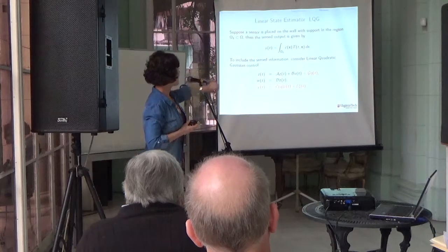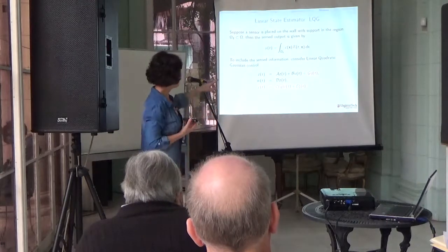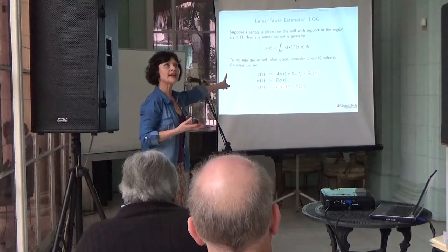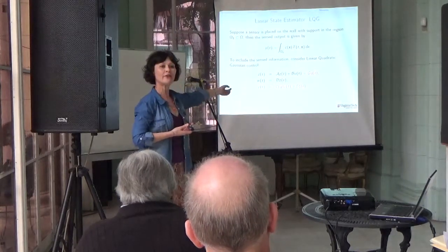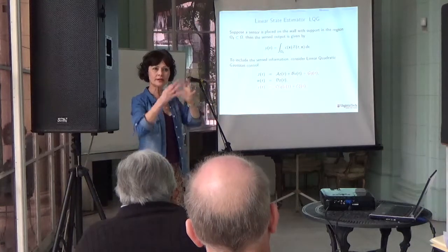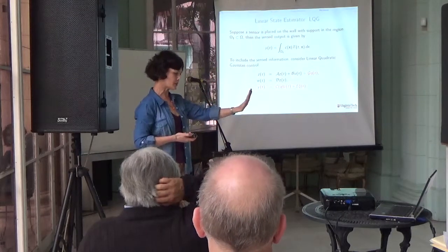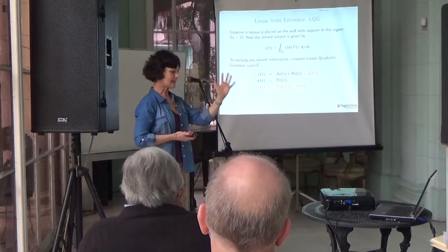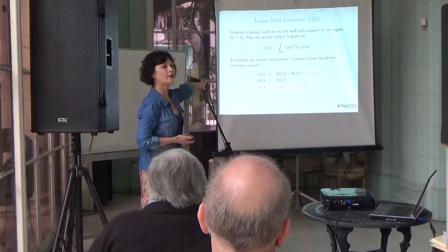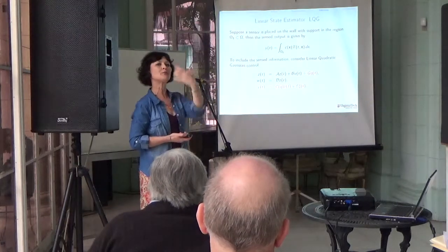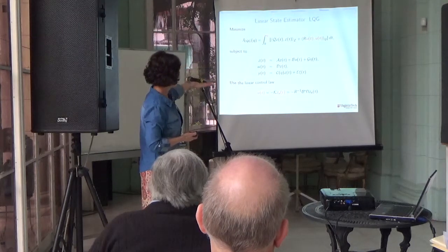But linear quadratic Gaussian control also allows for uncertainty in the model if one wanted to. G times eta will allow for dynamics that weren't represented in the model, and E times C will allow for measurement errors, for example. So that's the framework of that. So our idea is now going to be, I want to construct a controller. In the past, it was K times the full state Z. Now I don't know what Z is, I only have Y. So I want to use Y to make the controller. And the problem will then look like this.